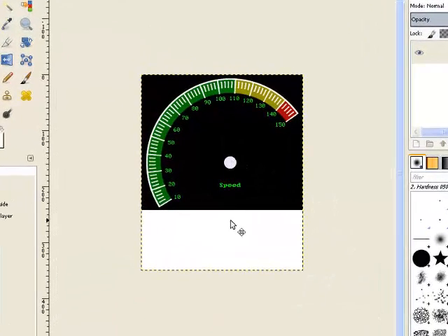The reason we need more room on the bottom of the bitmap is because the meter needle coordinate system starts with 0 in the 6 o'clock position, and it increases as it goes clockwise. For the meter defined command, we need to provide the angle of the needle at the minimum meter value and the angle of the needle at the maximum meter value. To do that, we're going to locate our pivot point, measure the length of the meter needle, and then measure the angles.